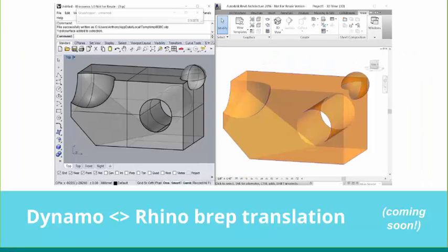Something that Jeremy might be particularly interested in, some of our power users in particular. Translating BREPs, boundary representations, from one software application to another can be very difficult, because although it's essentially the same geometry, they are represented in very different ways. What we've done at Flux is we've got access to very advanced translation tools to translate from STEP to SAB or STEP to SAT or any which way. And so very soon this will be released onto the main platform.